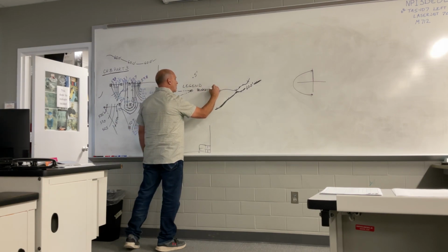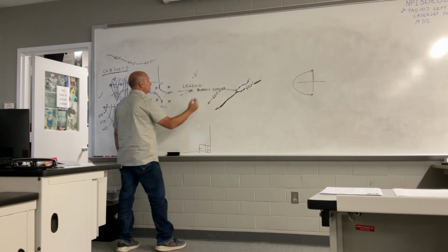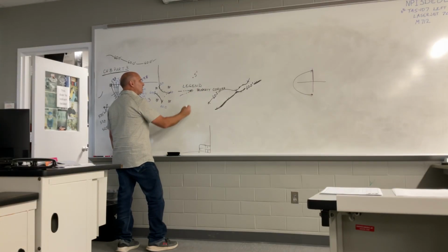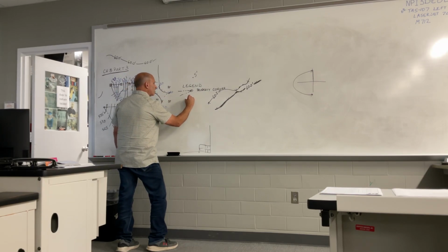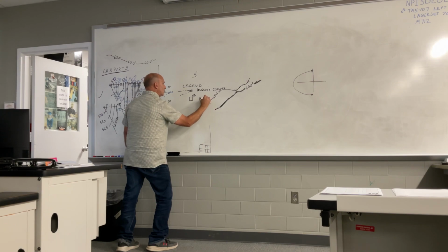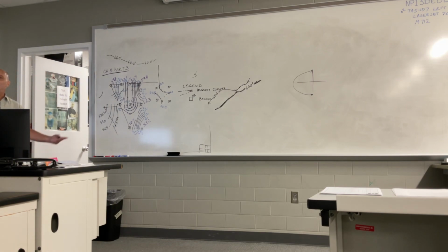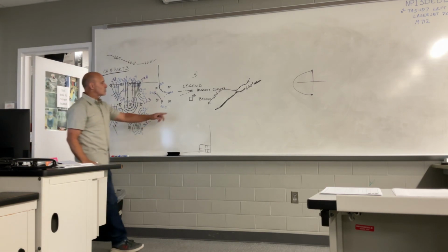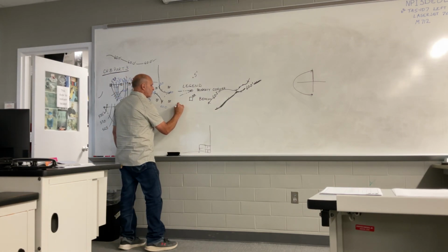I'm going to write this all the way out because some of y'all are still missing that right there. You're showing them a picture and you're telling them what it is. The next thing that you will still have on here is your benchmark down there. We are not going to have elevations on there, so it's just going to be the box with the BM above it. Tell them, hey, that's what that is. That's a benchmark. That little square with the BM written on the corner, that is your benchmark. And you're also going to have your index contours.